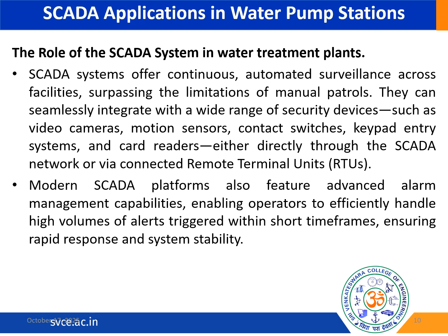So, if you consider the risk here, cyber risk is an ongoing issue in the large enterprise. So, this has to be eradicated. The communication network of SCADA is distributed across the water distribution system, and we'll be using workstations, typically PC based, situated at the treatment facility in the control room. This enables the operators to view the entire process, and we can take control measures.